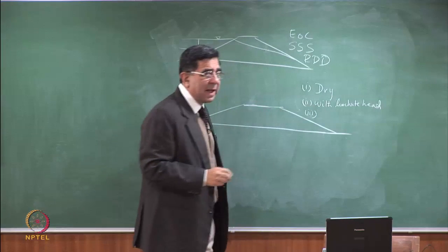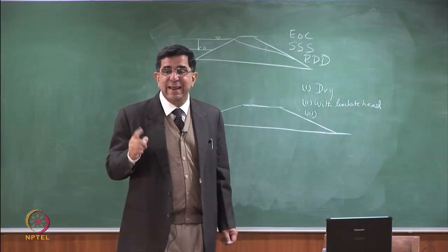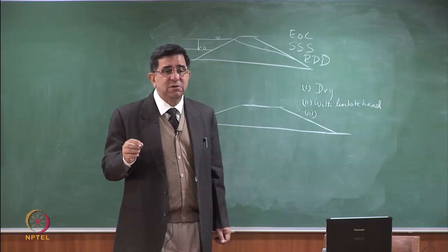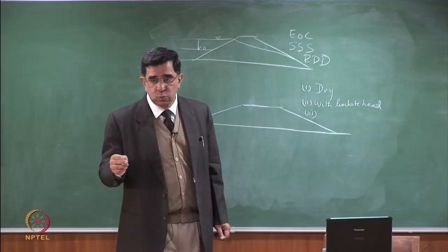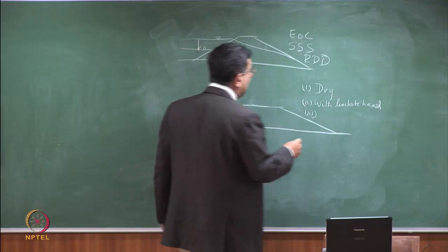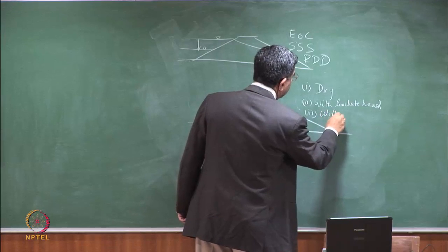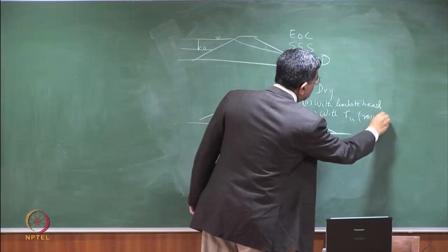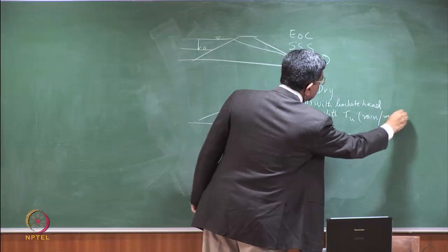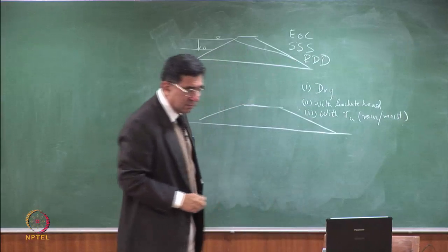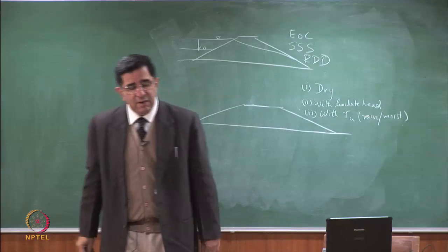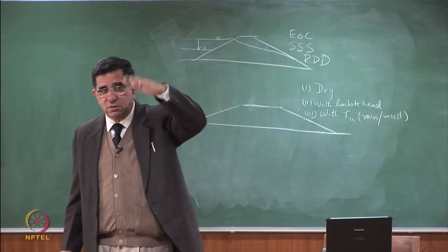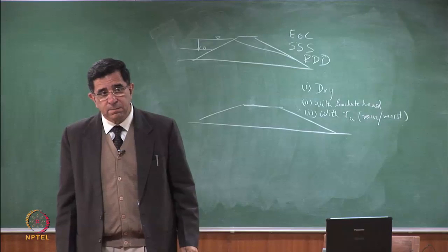When you do a road embankment, you also do an analysis with rain. And rain is simulated by a pore pressure parameter RU. So you can also have that, which means it is simulating rain or moist case, not fully saturated, but you have wet waste, therefore you are having pore pressure development as the layers come on top of the other.